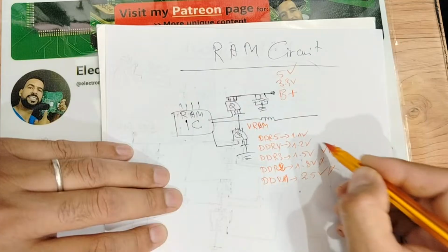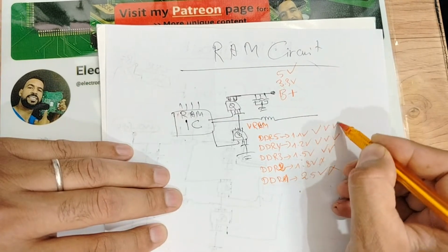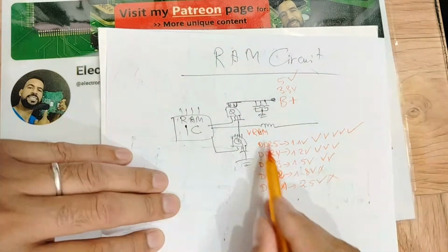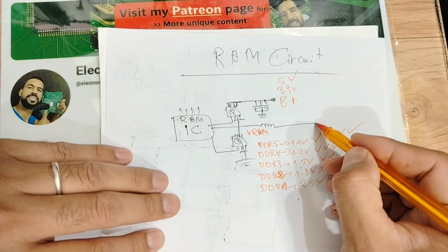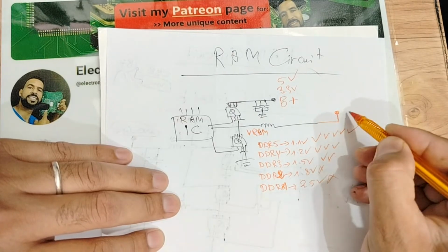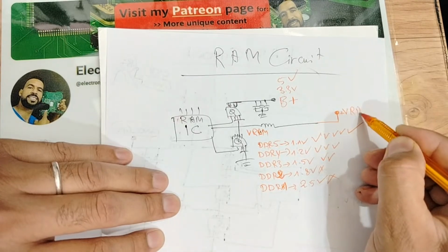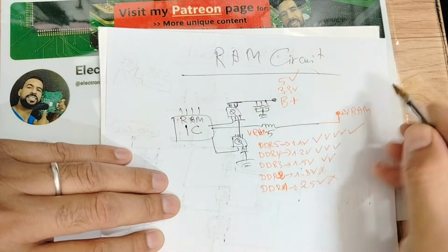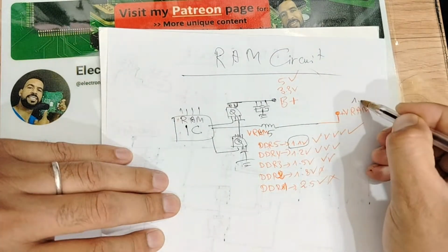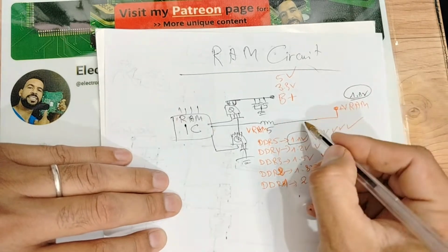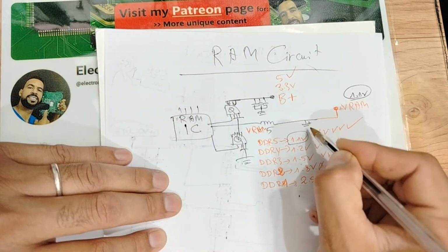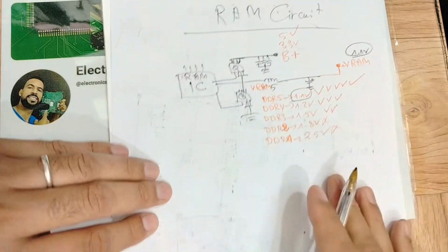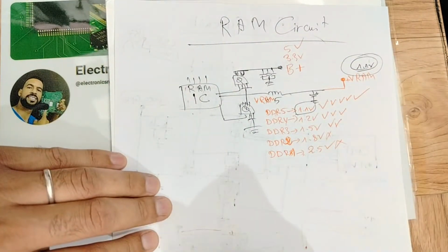Use it a little bit. This is the used one, DDR5. Depending on the type of the RAM, we will get the RAM voltage here. If the RAM is, for example, DDR5, we will get 1.1 volt for the RAM. Of course, here we also have electrolytic capacitors for filtering and an inductor. But for the RAM, this voltage is basically 1.1 volts.